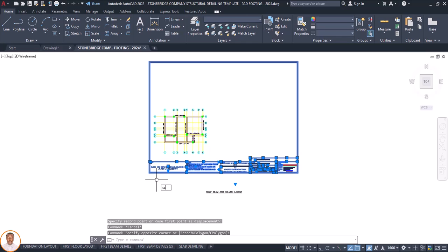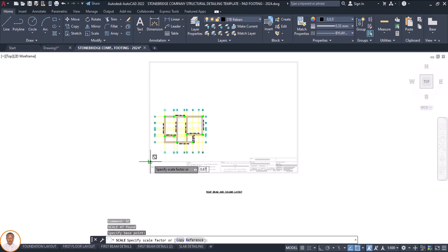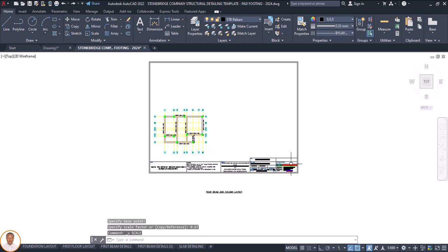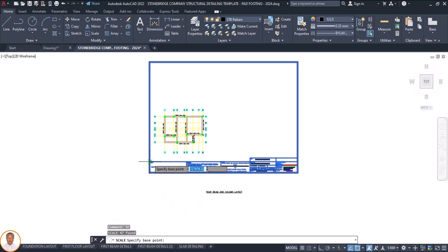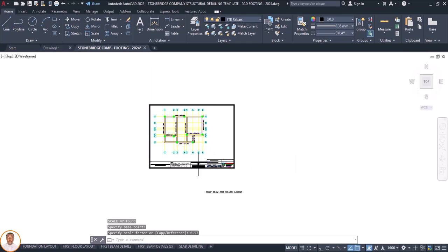That's SC, that's scale. Come to this edge here, 0.67, enter. Let's wait for it. It's small, it's still big. Undo it. Then 0.67, that's what we use, isn't it? So I now press SC, enter. SC stands for scale. I'll come to this point here, click on it, 0.57, enter. See, almost. Yes, you can leave it like this.